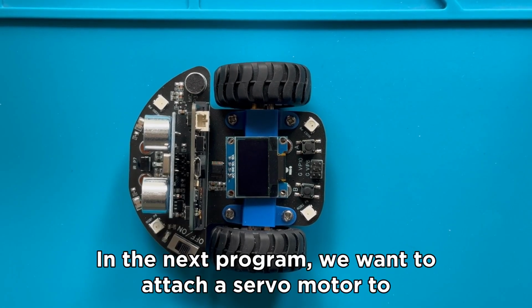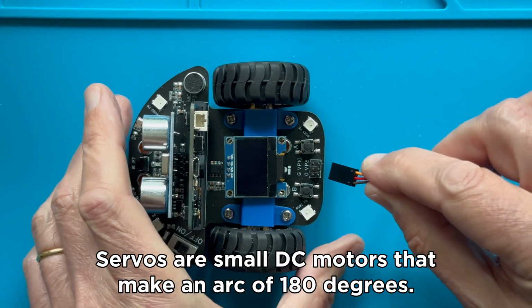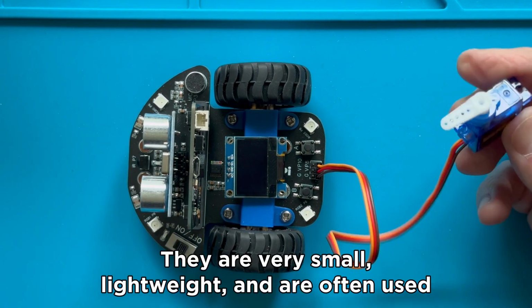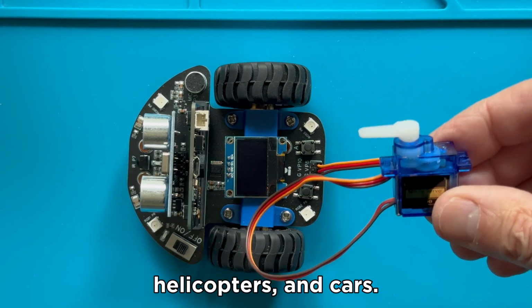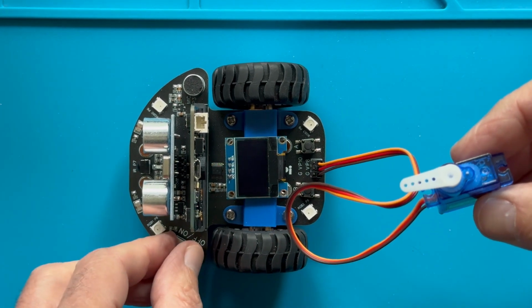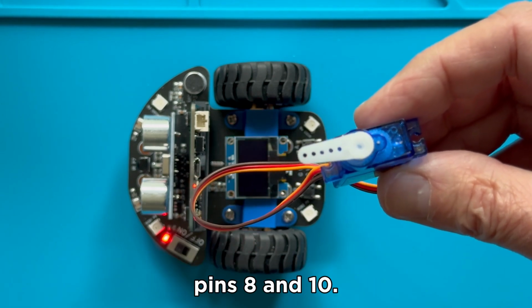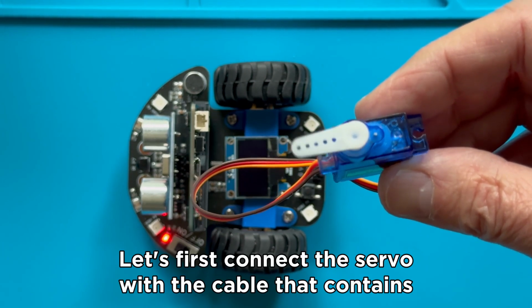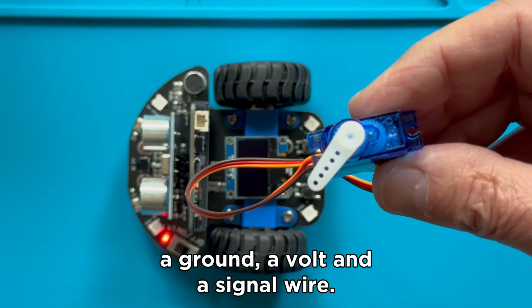In the next program, we want to attach a servo motor to the robot car. Servos are small DC motors that make an arc of 180 degrees. They are very small, lightweight, and are often used in remote-controlled airplanes, helicopters and cars. On the microcar, there are 2 external connectors linked to pins 8 and 10. So let's first connect the servo with the cable that contains a ground, a volt and a signal wire.